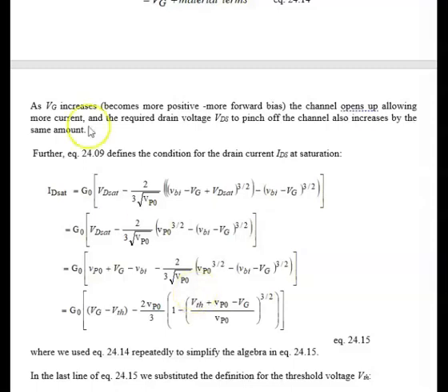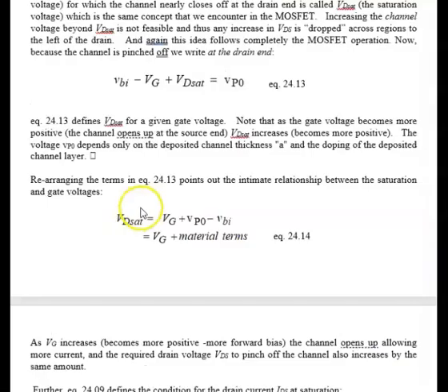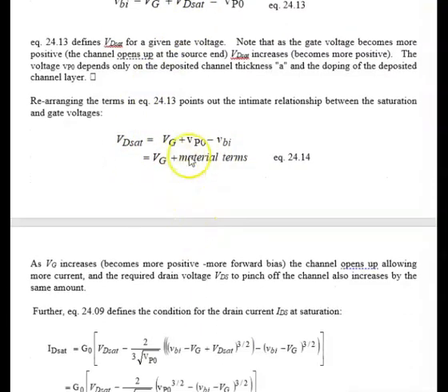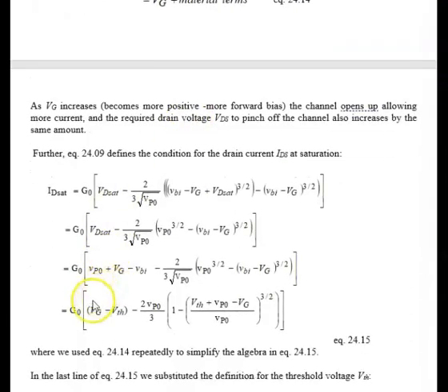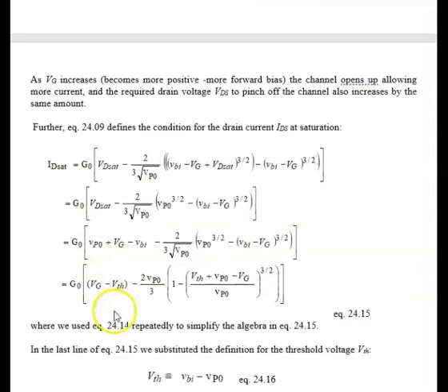Okay, and now we continue. Now we substitute for VDSAT, back here or here, doesn't matter. We substitute the three terms for VDSAT. Now this term turns into all this, and here this remains the same. And finally, we pull a VPO out of this whole mess, and lo and behold, we can define something now called the threshold.